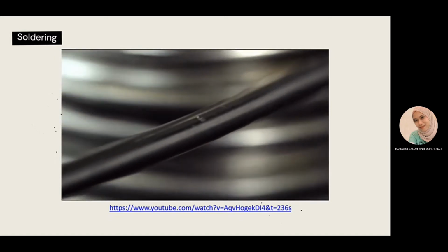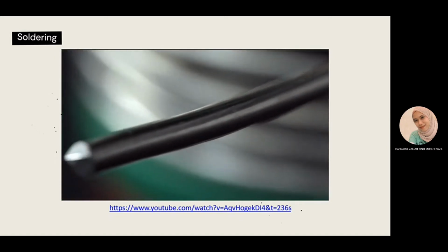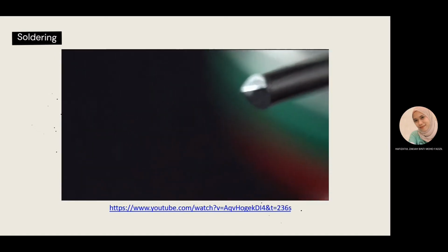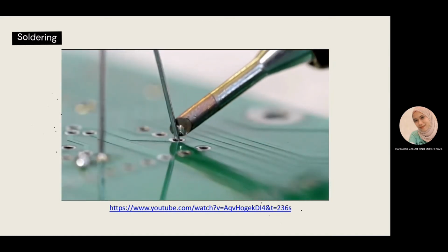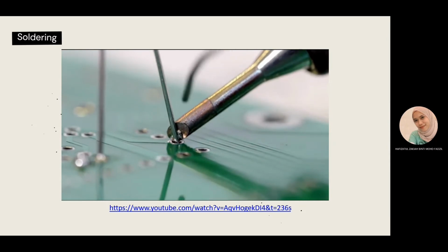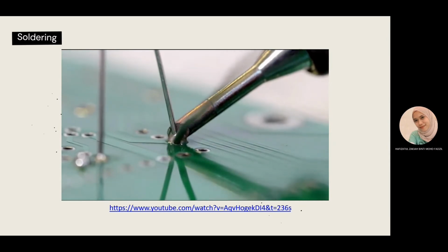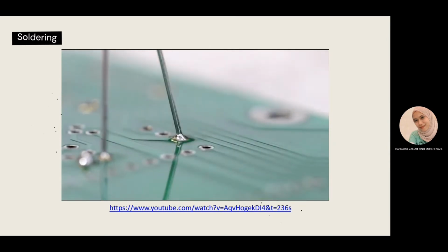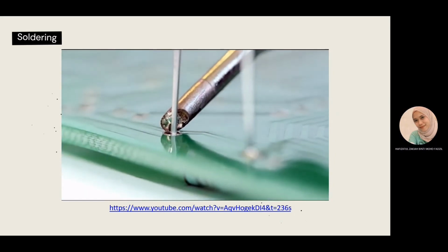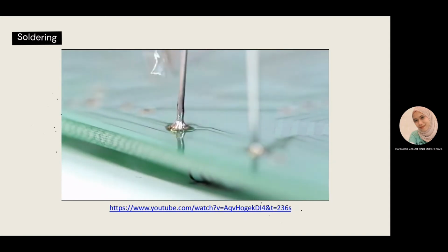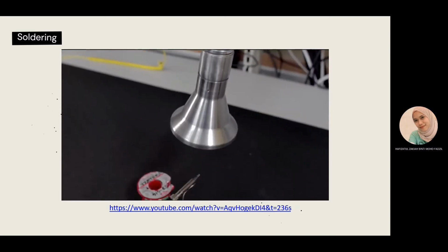The other item you'll need is of course solder. Solder is a low melting point alloy which flows easily when heated to its liquid state. When it cools and solidifies, it fuses to the surface of a metal at the molecular level, providing good electrical conductivity between two metal surfaces. Solder normally contains flux, which helps the solder to flow, and also helps make a good contact by removing the oxides on the surface of the metals being joined.